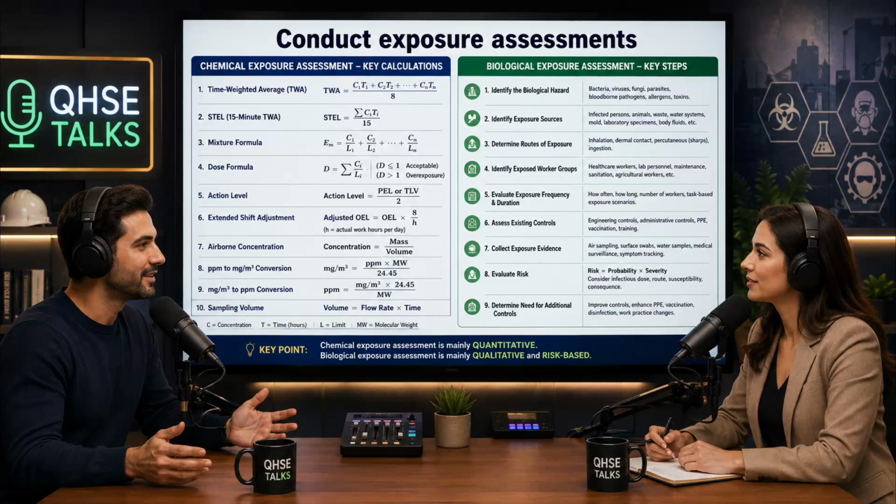That's super fast. You can also get long-term diffusion tubes that passively draw air in over an 8-hour shift. To find the TWA, you just divide the final scale value by the total hours sampled. They seem brilliant for immediate field screening. You don't have to wait 2 weeks for a lab report to know if the room is deadly right now. But what is their weakness?